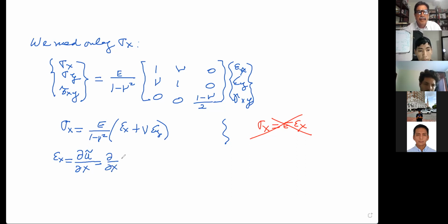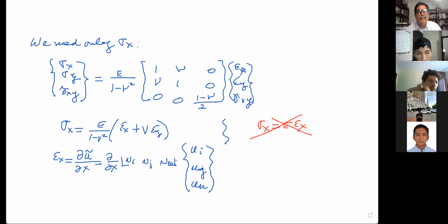Remember that we have ui, uj, and uk, and here ni, nj, and nk. Each one of these is 1 over 2a times alpha plus beta i x plus gamma i y.